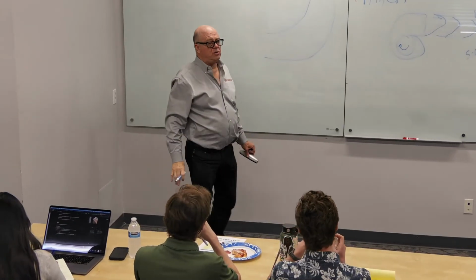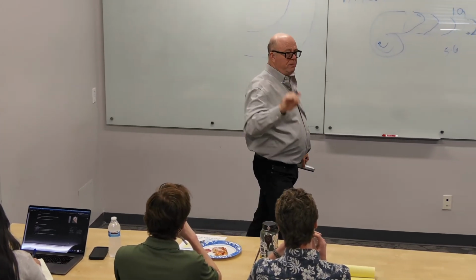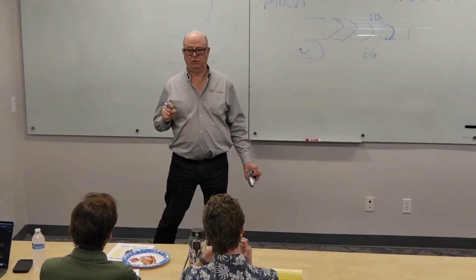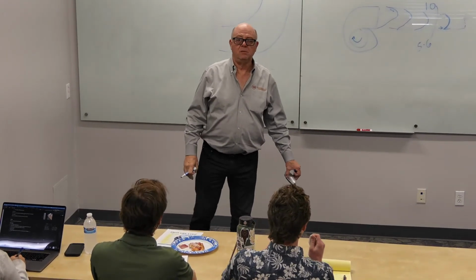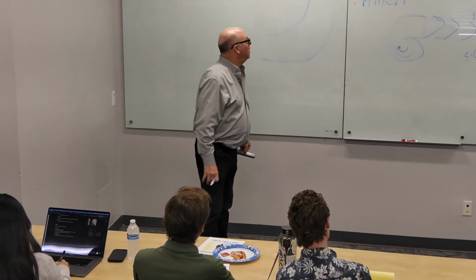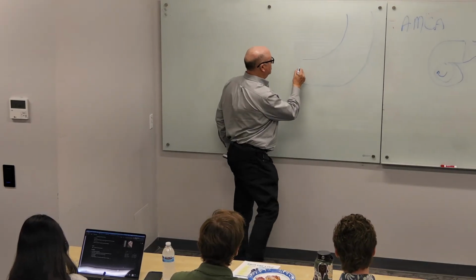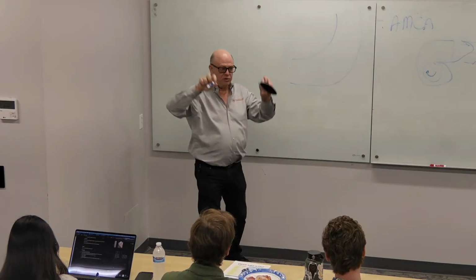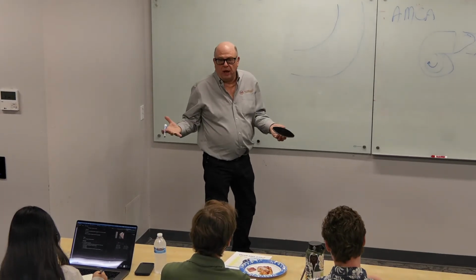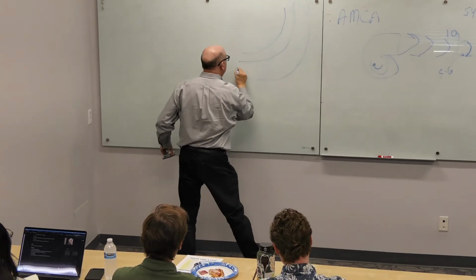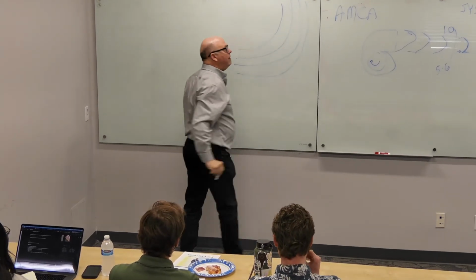And it uses what our sheet metal guys here in Southern California call splitters. I had never heard that term before I moved to California. What we're really talking about are full radius turning vanes, which if we wanted to put in 2 splitters, you can see why they would call it that, right? You would have one that does this and one that does that.